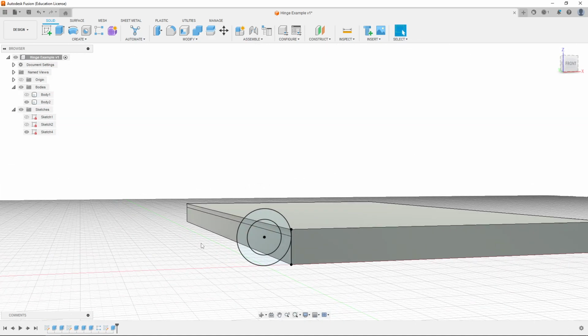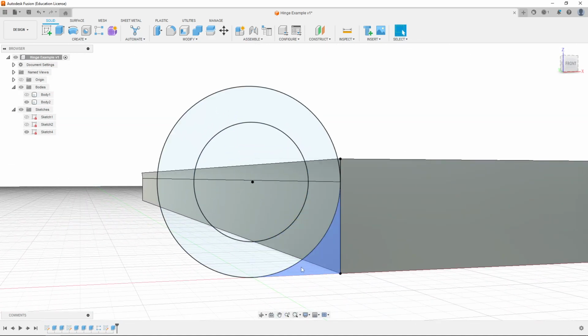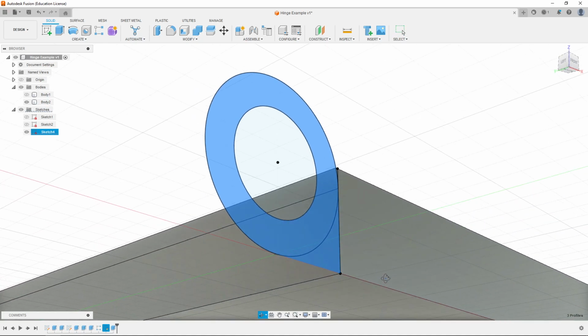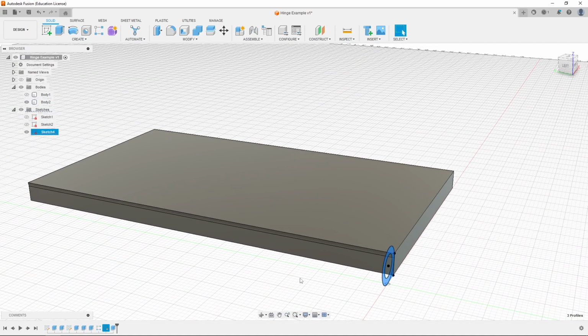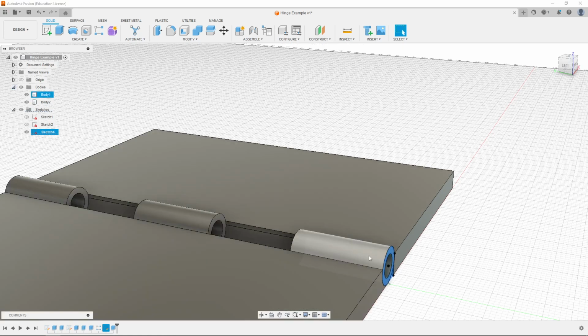And now my extrusion. What I want to do is extrude the solid part, which will be both this part of the ring, this part, and this part as well. But that's only for this side. Now if I extrude this again all the way through, that's going to be blocking or overlapping with body 1, so I actually want to offset the distance of a solid part of body 1. So I don't want to actually overlap with this piece, so I should start at this ring right here.